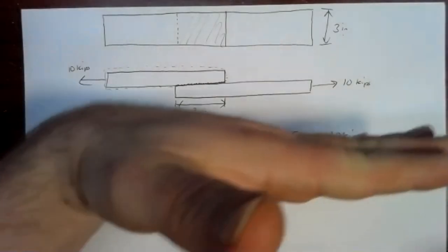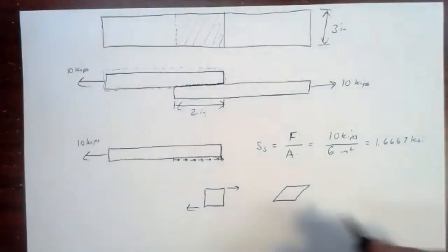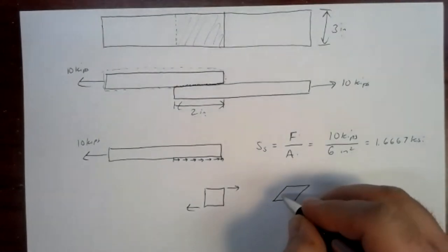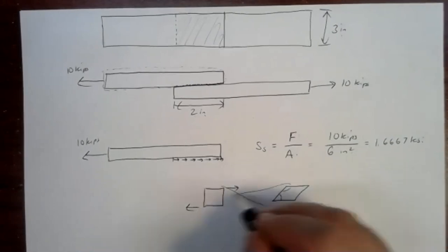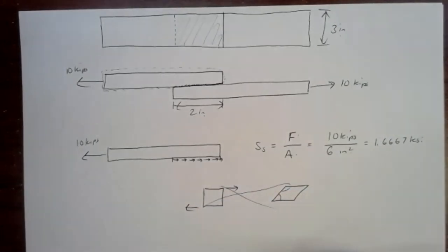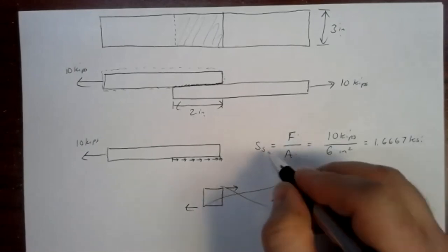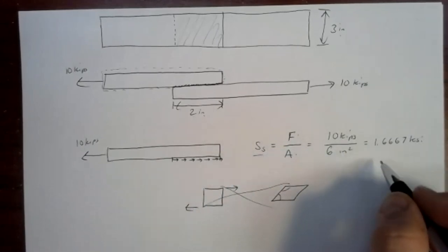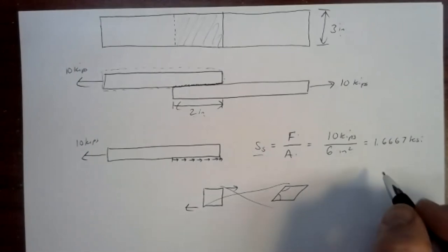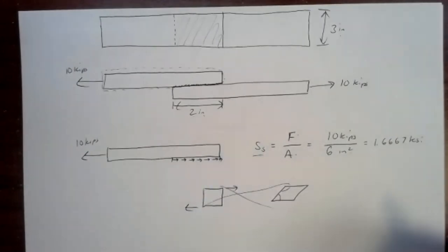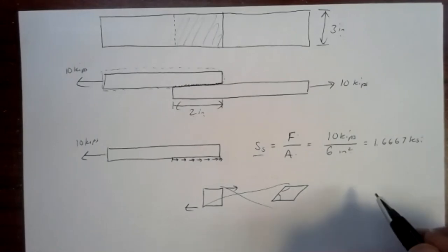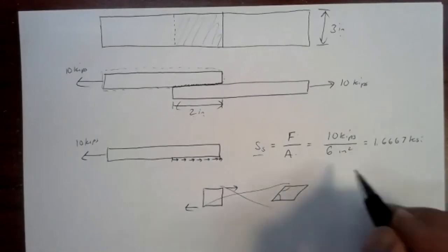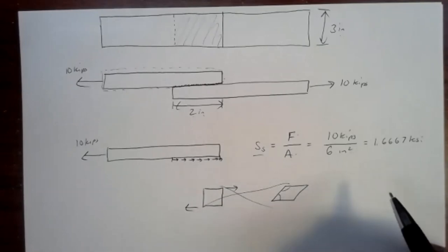So if you took the top and the bottom and slid them against each other, it would tend to rack like that. You actually measure shear strain in terms of the angles. That's not terribly useful from a structural standpoint, so we never really bother with it. The thing we worry about most with shear stresses is calculating how much shear stress there is, so we make sure we're well away from the limits of the material holding the plates together. We're not worried about it deforming, we just don't want it to break. And we'll see that in several of our analysis exercises later on.